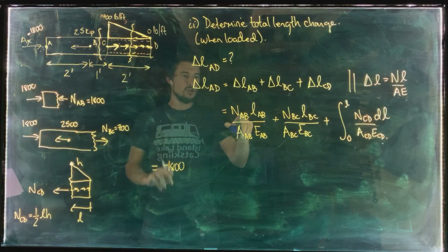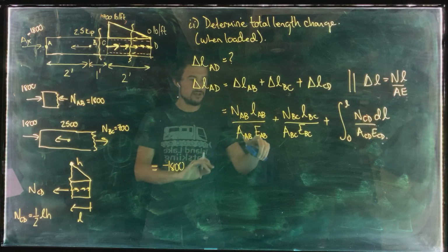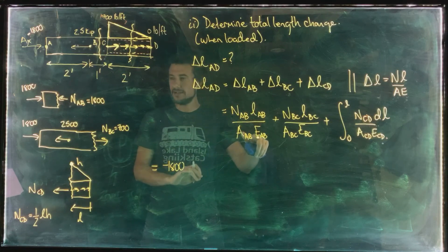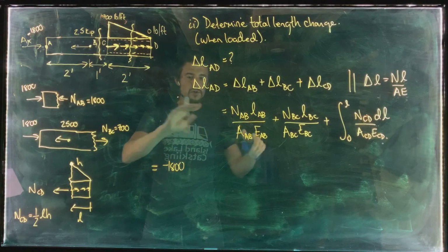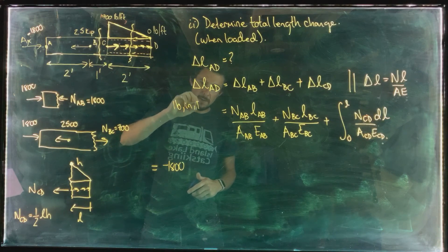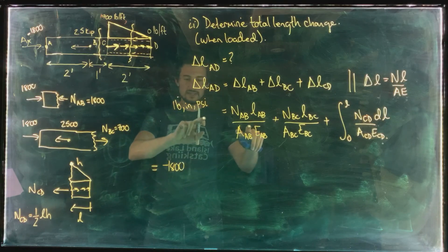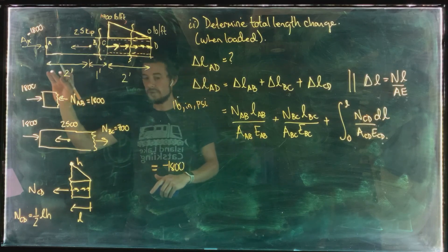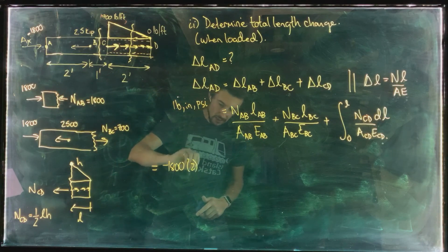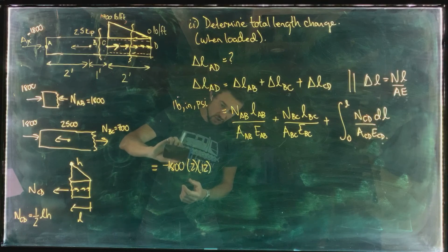Now, remember, when you're using equations that involve stress or things that are related to stress, like modulus of elasticity, you want all of your numbers to be in pounds, inches, PSI when they go into this type of equation here. So I'm going to take that 2 feet and multiply it by 12 to change the feet to inches.